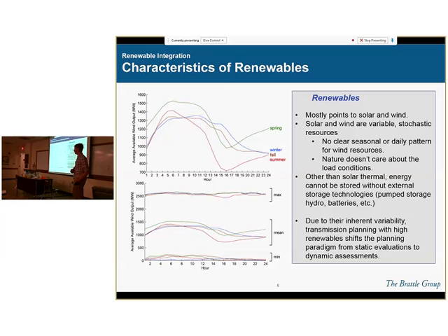You haven't defined flexibility, have you? I can talk about flexibility. I guess I was just saying flexibility is the ability of the system to respond to changes. So, for instance, if there's a large ramp in the renewable, there isn't really a single metric that's been defined for flexibility, but we often talk about flexibility in terms of the ability of the system to respond to ramping. That's one proxy for flexibility. Ramping is defined as the rate of change that a generator can go through over the time it takes to go through that. So for instance, like 10 megawatts per minute. If it can raise its output 10 megawatts in 1 minute, then that would be its ramp rate.